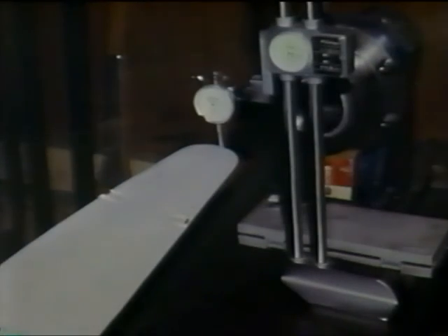The first step in blade overhaul is the precision measurement of blade width, thickness, face alignment, blade angles, and track. Blade width is accurately checked with a vernier caliper at stations along the length of the blade. These dimensions are specified by the propeller manufacturer. Thickness measurements are also taken along the same specified intervals. Measurements are recorded and double-checked against the manufacturer's overall specifications. Blade track is checked and recorded.